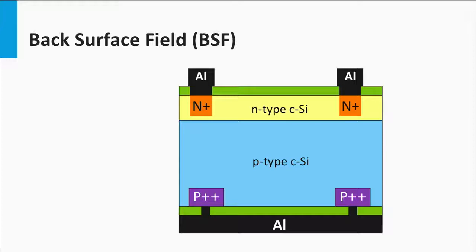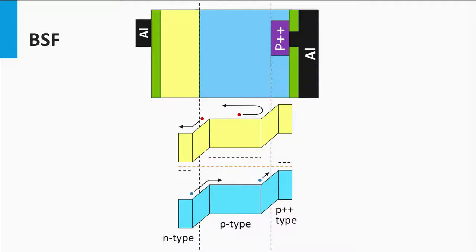How does the back surface field work? For the moment we have put the solar cell on its side. Below the solar cell you see the band diagram indicating the various interfaces. The interface between the lower doped P region and the higher doped P region acts like a PN junction. In this case, it will act as a barrier for the light-excited minority electrons in the lower doped region to diffuse to the back surface. The space-charge field behaves like a passivation of the defects at the back contact interface and allows higher levels for the electron minority density in the p-doped bulk.